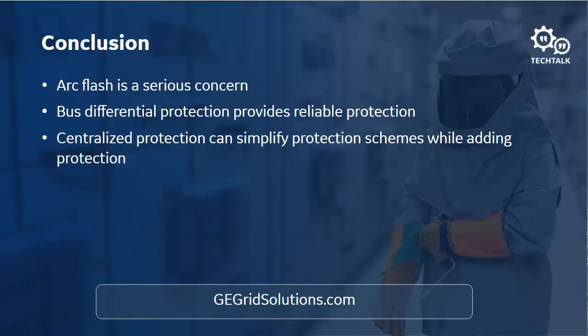So here's a question: how is using high overcurrent instead of bus differential advantageous for arc flash protection? As we talked about, just high overcurrent is not as advantageous compared to the bus differential because you need to use time to coordinate it properly. The maintenance switch gives you the possibility to just miscoordinate that and get some high-speed clearing, but then you do have the potential for human error and it not being put back into the proper running condition when maintenance crews leave.